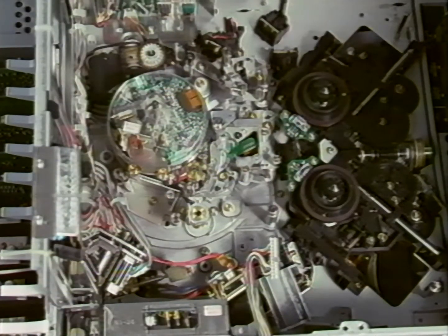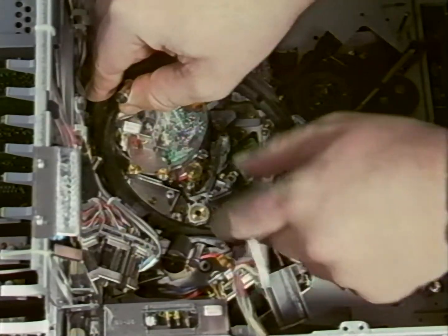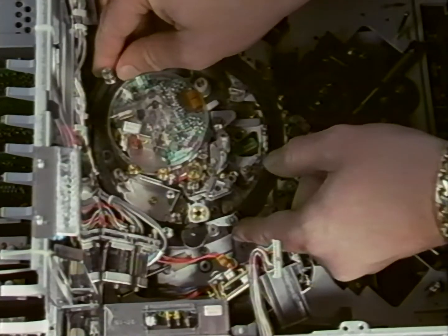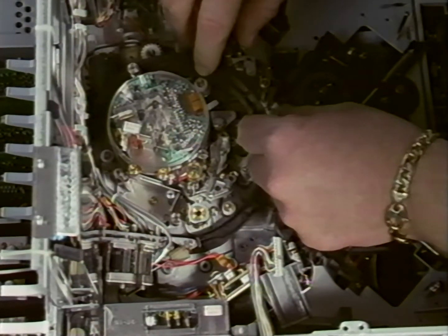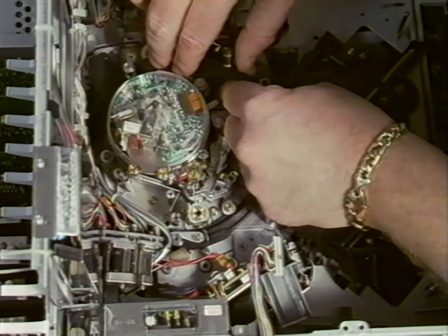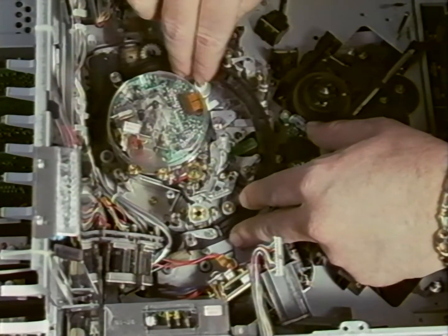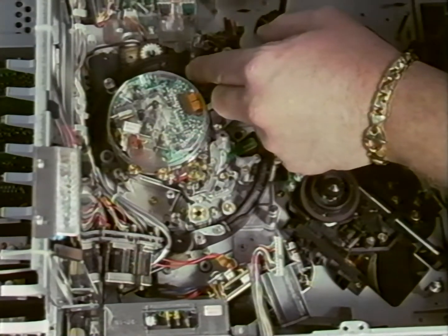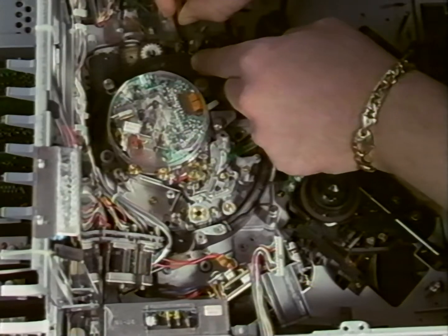The threading ring is shown being installed now. Note that the reference for the position of the threading ring is that the pinch roller should be positioned in front of the audio assembly. As the ring is placed back in the machine, the T-drawer arm is moved out of the way, and the threading ring is positioned between the rollers that control the S tension regulator arm and the rollers that control the T-drawer arm.